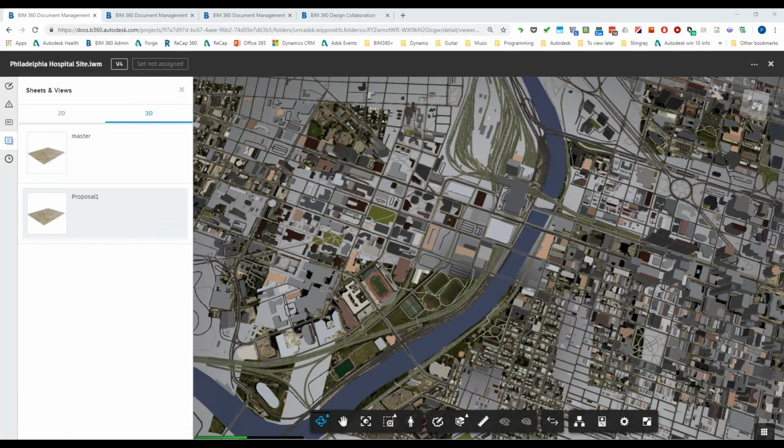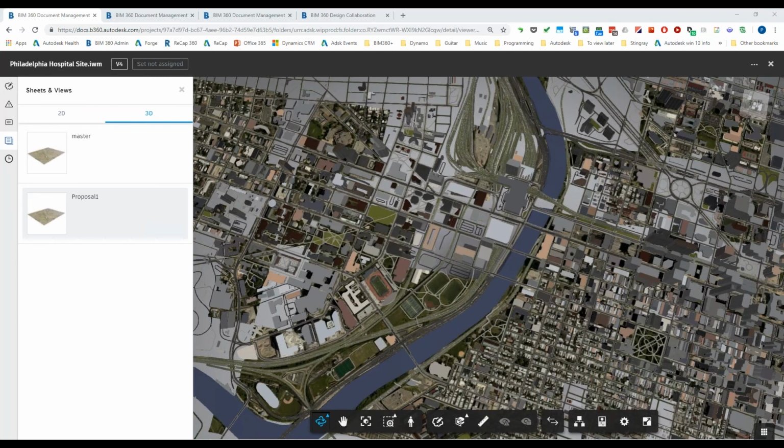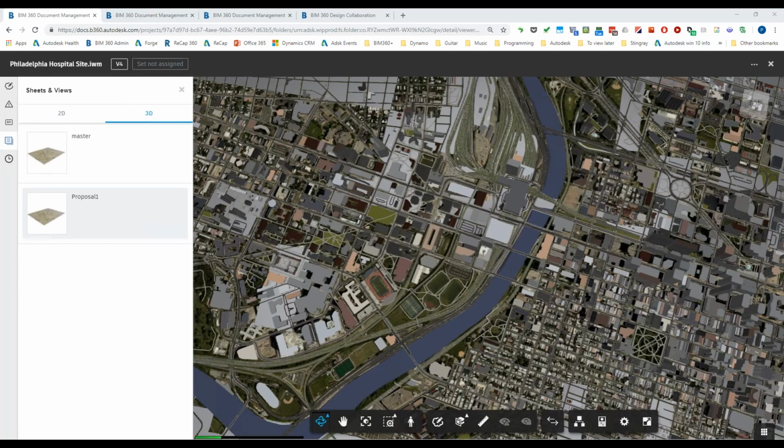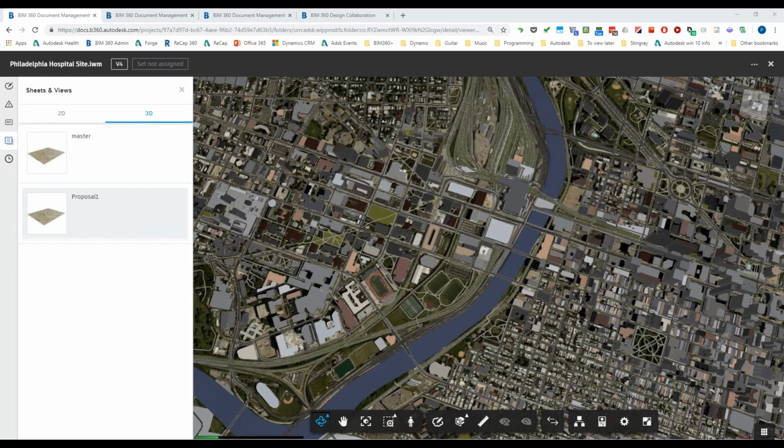Good question. If the architect inserts a building pad in Revit, can the civil engineer import that into Civil 3D to edit the topo surface? So at the moment, this workflow is one directional, meaning that the civil engineer is pushing the data into Revit. Now, the Revit user can export out to CAD or to send information so that the civil engineer knows where that is so that they can edit and adjust the topo surface.